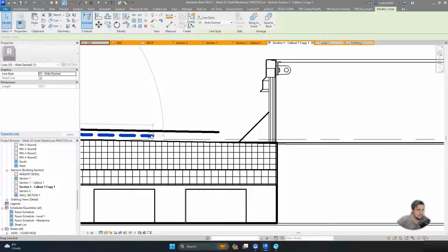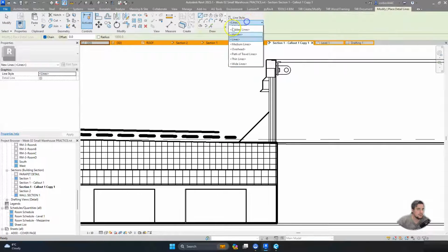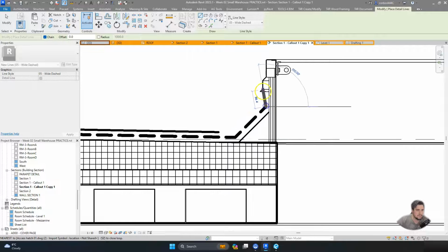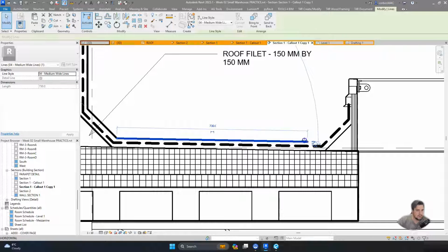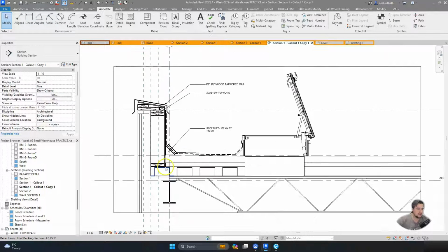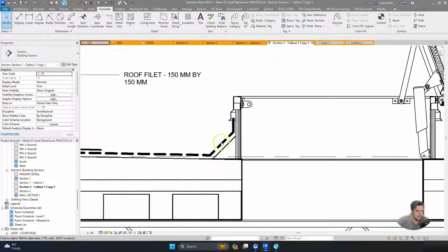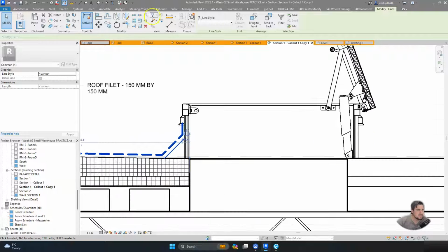So we would have this membrane coming across like this, and it will then extend up those lines like that. And this piece will probably not go all the way. It'll probably stop something over here. Again, it's just kind of to protect that corner. And then we would copy this stuff over to the other side of this skylight.